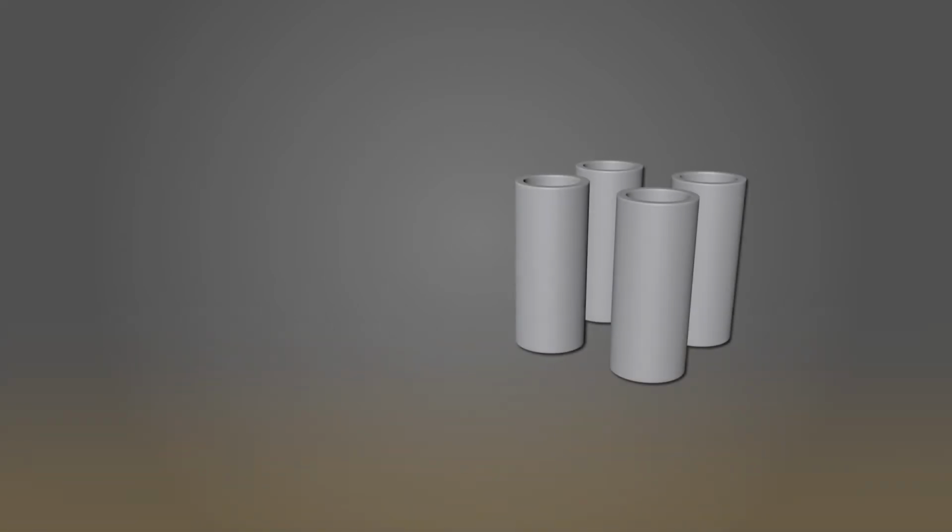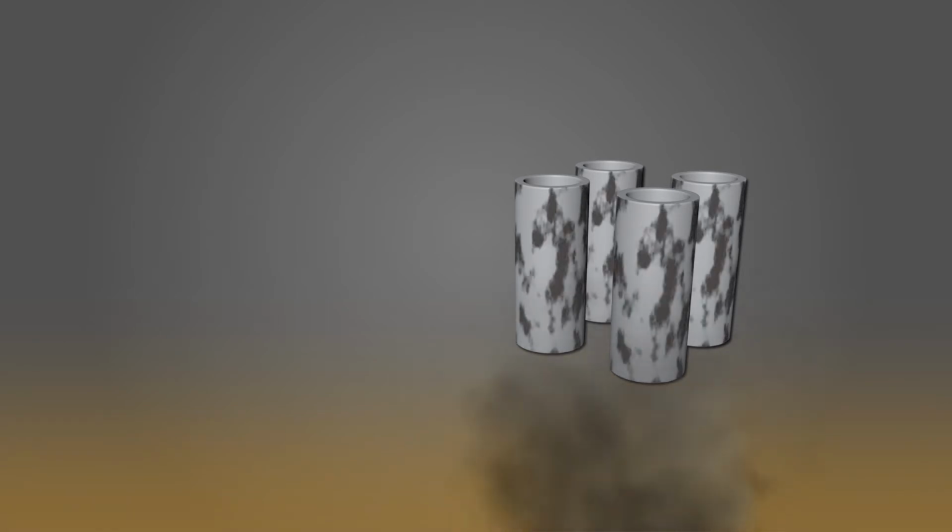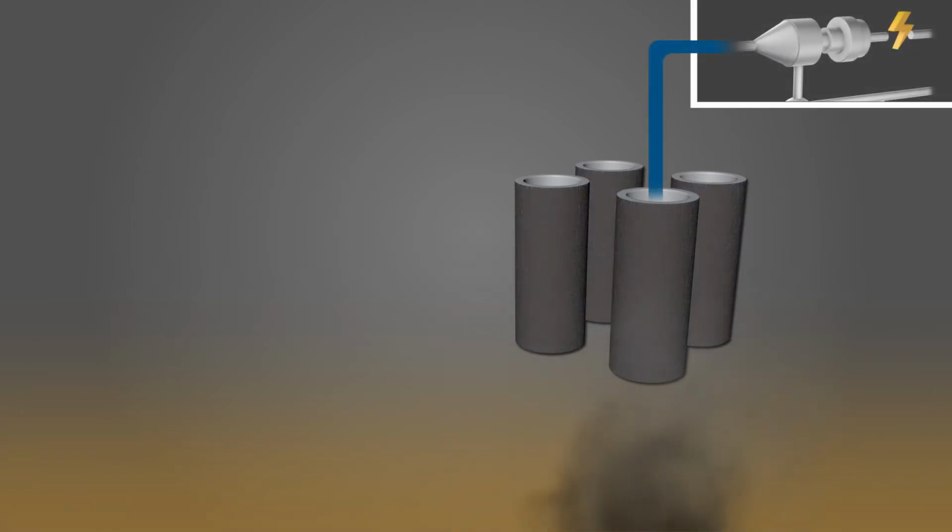One problem with combustion is the resulting ash in the flue gas, which causes fouling and slagging on the surfaces on the fire side of the boiler. The fouling inhibits the important heat exchange from the hot flue gases to the steam, which is used for power generation.